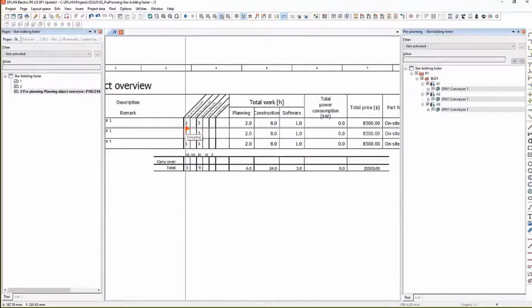And now look at that. It added all of the signals needed for each one of these objects, giving me a total number of signals. So right then and there, I don't have a drawing yet. I just have an understanding of the control systems that I'll need. I also have a number of IOs or signals needed for that particular system. So there I can already start sizing my PLC system and maybe go to the various different PLC vendors and asking them what type of PLC could support that type of system.